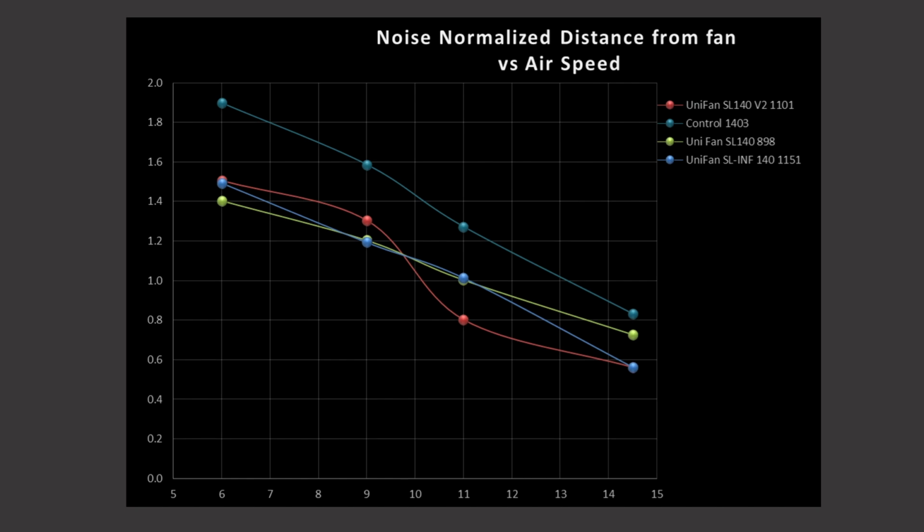So with all of that said, this composite control fan is there to be a general baseline mark: fans that are over it are considered good to very good. Fans that are basically at the line would be considered good. Just under it could be considered good to okay. And if they're way too low, then they'd be considered very, very poor performers, in this case, in an airflow type test. And so what are we seeing?